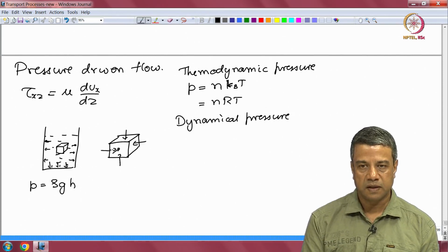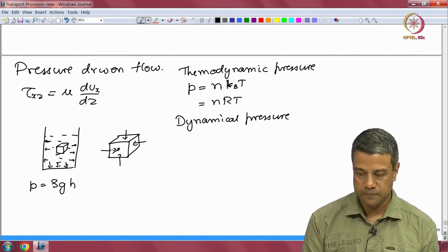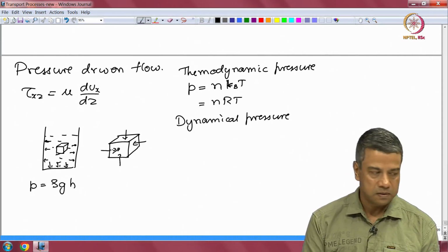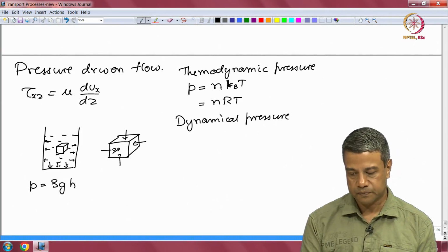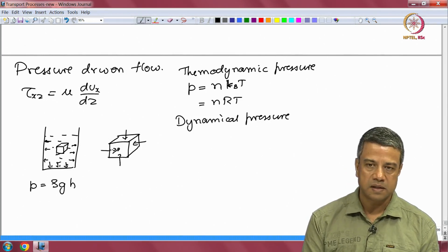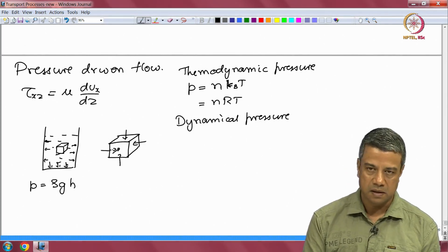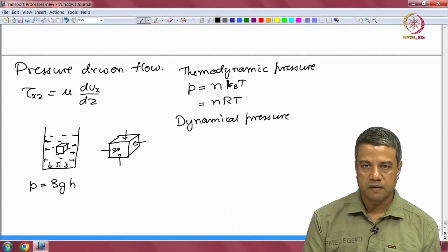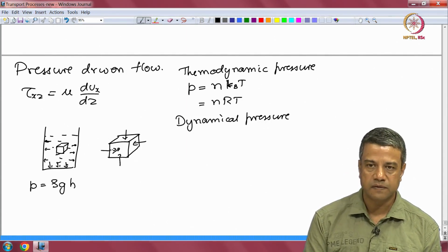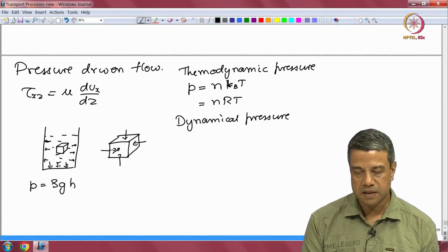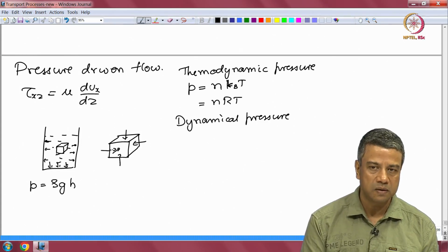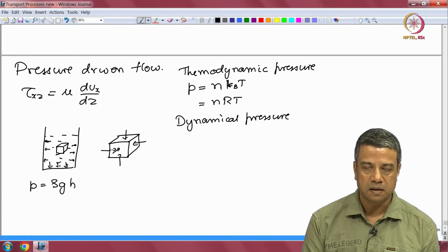So, if you have a pressure field which is generating a certain flow, incompressible flow, so we assume that the density is a constant, and so the pressure field is generating an incompressible flow. If you add a constant pressure everywhere, in the equations of motion, the velocity field will not change because the velocity depends only upon variations in pressure.